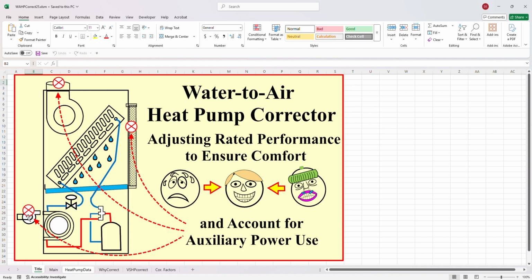In addition, the power of the fan required to circulate air through the duct system, the grills and the filter needs to be included. This power also turns to heat, and so that heat must be deducted from the total cooling capacity of the machine. Fortunately, in heating, it's a benefit, so it's added to the capacity.